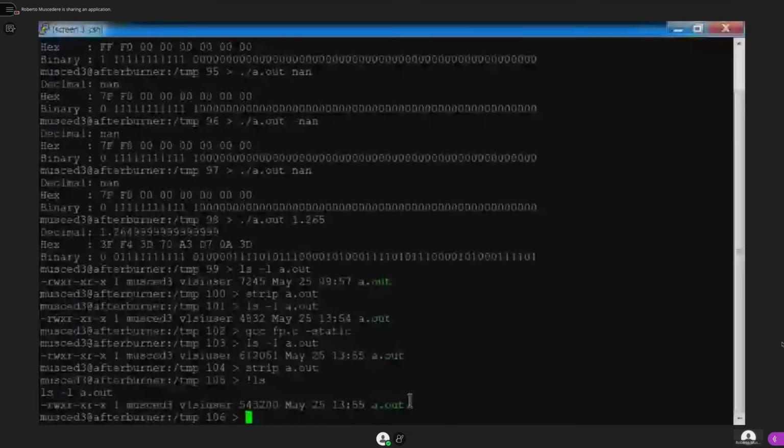Whereas I could just get a simple microcontroller and do BCD arithmetic, and the code could be maybe less than a kilobyte of memory. Okay, but what was easier to write? Well, if I just wrote a piece of C code that took the number, added 1 to it, and then used printf to show it to me, sure, that'll work. But it's far larger than it ever needs to be.